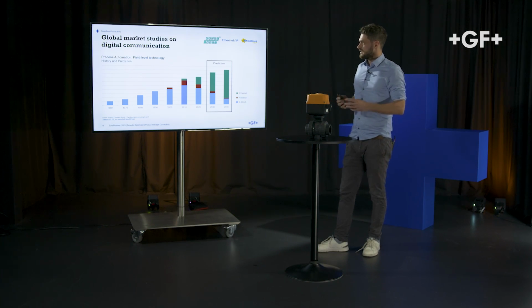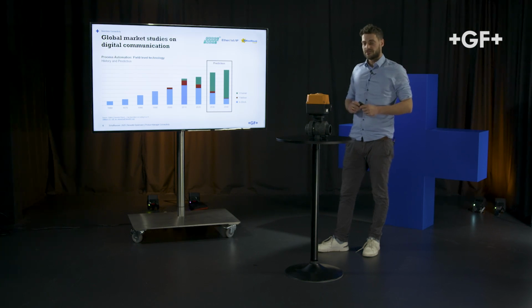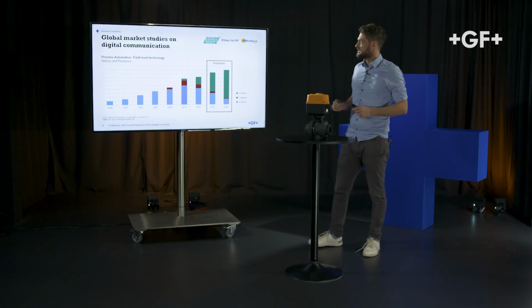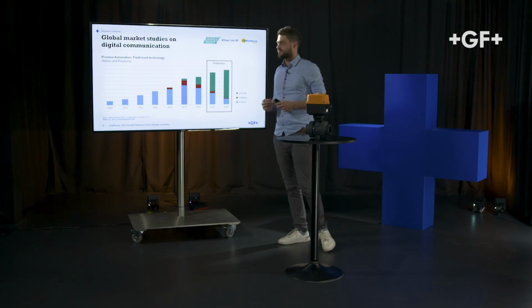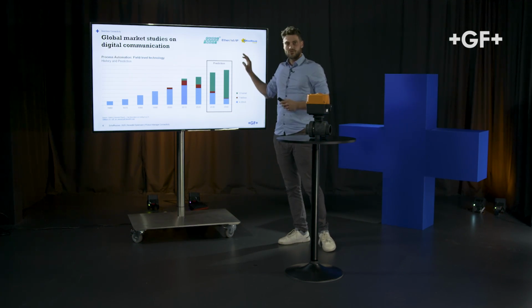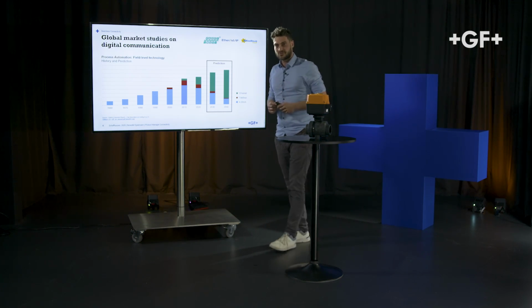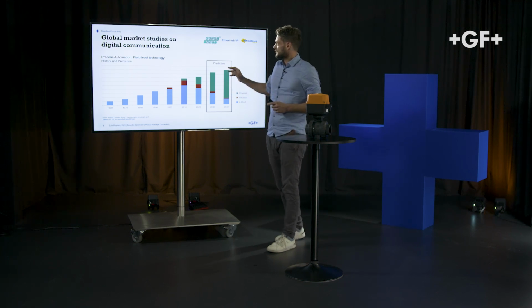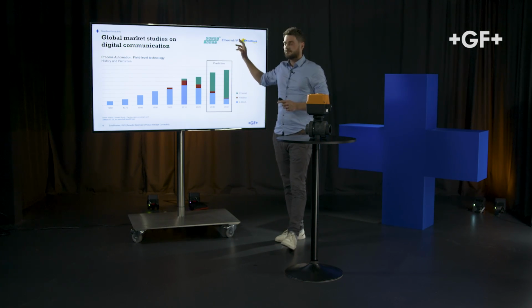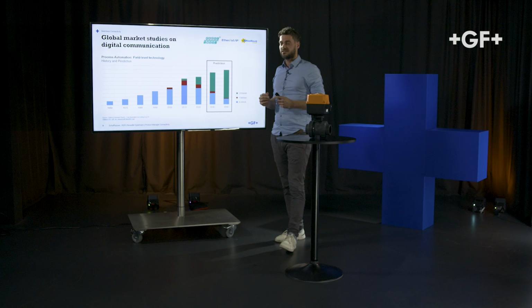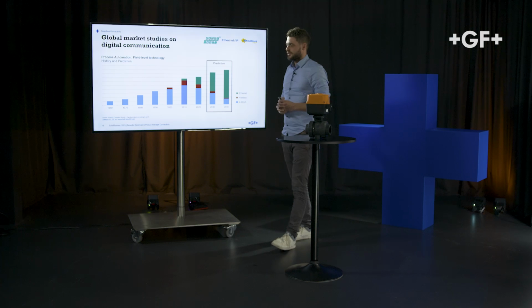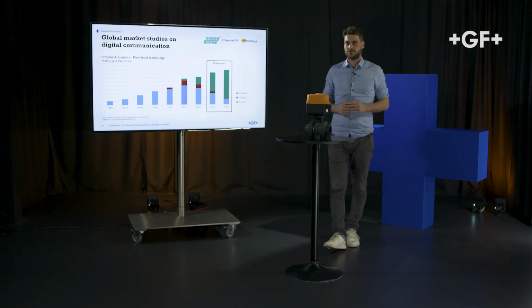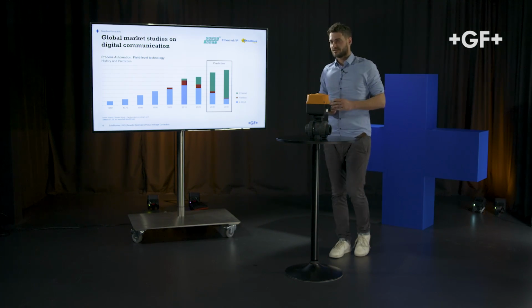When we talk about Ethernet in the world of industrial environments, there are 3 most important industrial Ethernet protocols. We will take a look at those protocols in later episodes of this video series, but just so that you have heard about it: Profinet, mostly associated with Siemens environments, Ethernet IP, associated with Allen Bradley or Schneider PLCs, and Modbus TCP. Those are the most important protocols in terms of industrial Ethernet.